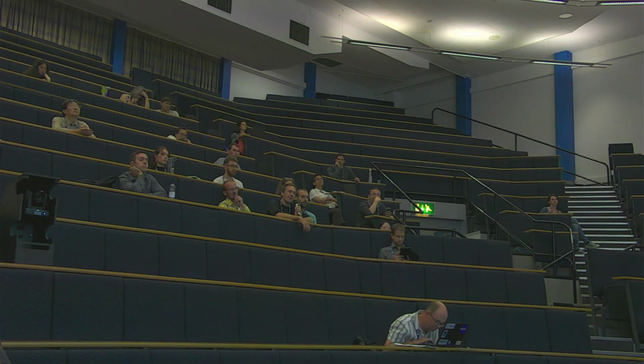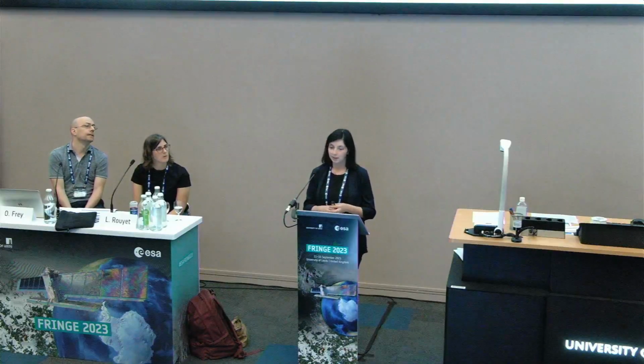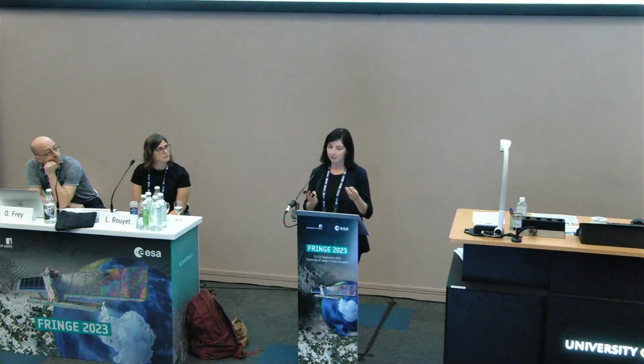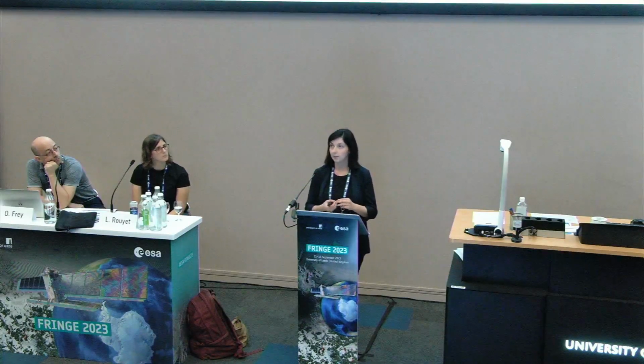Yeah, I think when we're looking at the CPD, we are looking just at the HH and VV polarization, and from this coherence region, we are taking different combinations of HH plus VV and HH minus VV, and apparently there is some kind of combination of these Pauli parameters which have a higher phase diversity than just looking at the CPD.